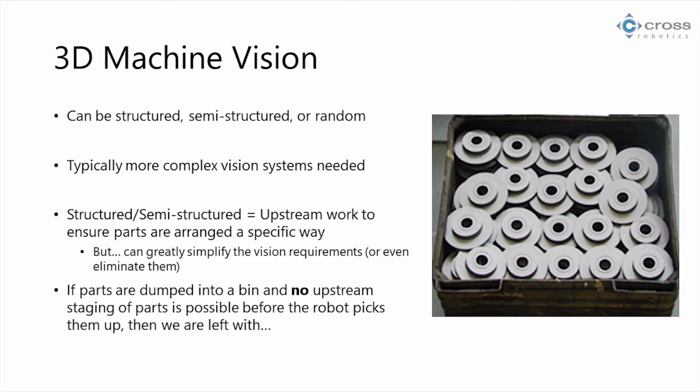So 2D machine vision in this case tends to be, now I'll let any of our technical guys jump in, or we can catch up after the presentation. 2D machine vision, when you're picking with a robot, most of the time what it's doing is, you've trained it what to look for, and then it finds the best match out of what's in front of it. So it just finds the best match and tells the robot to go to it. I'm not saying you can't do what you're saying. It adds complexity to your programming, and there's a lot more thought in it. So in this case, we're just talking about locating a part, moving the robot to it.